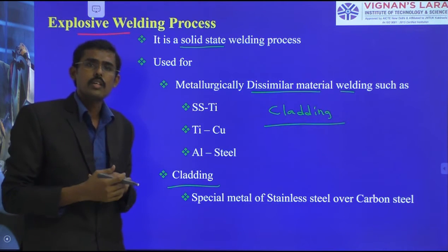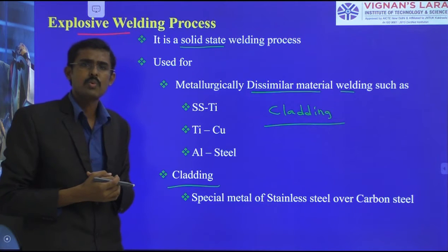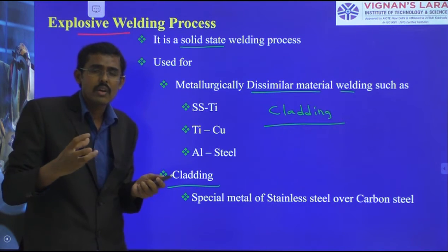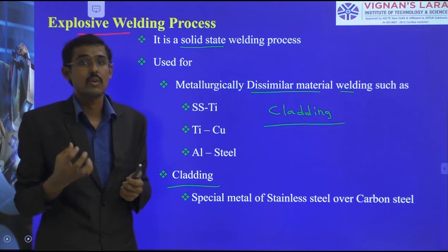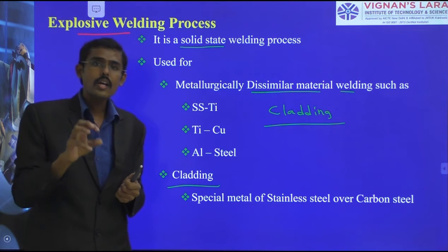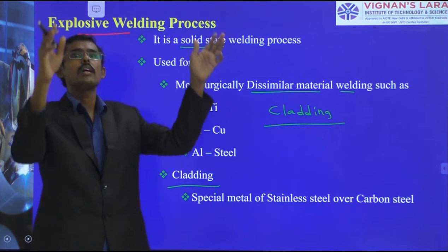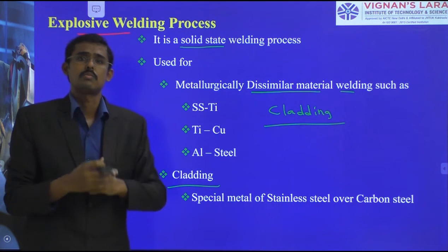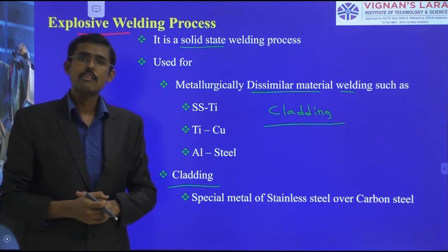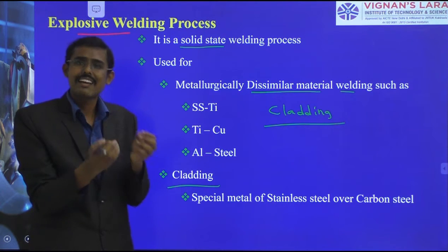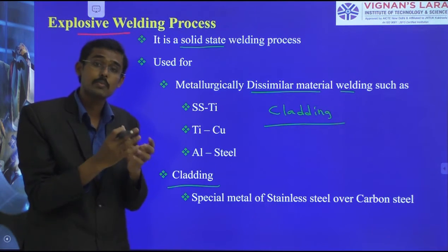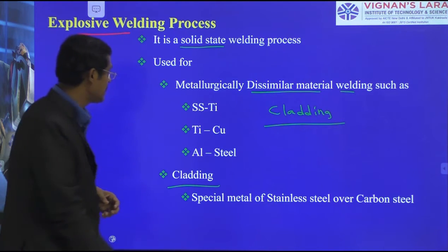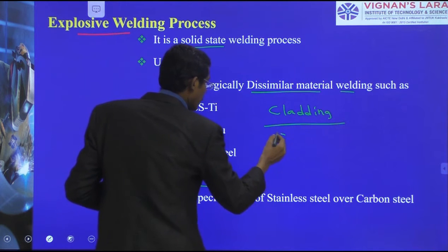In boiler components, due to the steam process in hot conditions, the material will start to erode and corrode. To avoid this, the entire boiler plant could be made of stainless steel, which is a corrosion resistant material. But the entire boiler cannot be made of stainless steel, because pressure maintenance and mechanical strength are very important here.